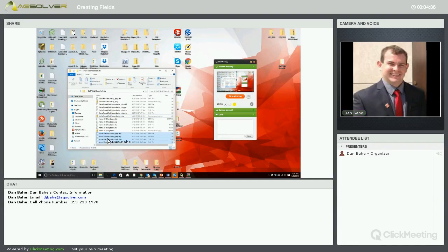We'll select the dbf, prj, shp and shx. Select all of those. Left click, send to compressed zip folder. Now we've created a compressed zip folder of our shapefile that we exported out of SMS.